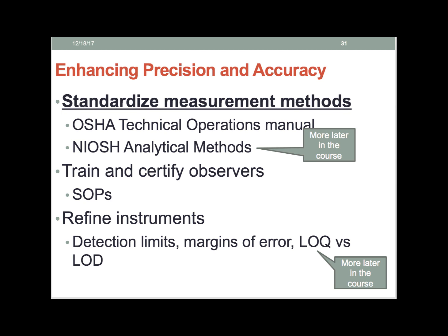And these can actually be easily confused with one another. So we may choose a different method based on the confounding variable of having too much dog hair in our environment. And for precision, precision would be ensuring that we pre- and post-calibrate our pump, that we handle our media in the right method that is appropriate for it before we sample, during sampling, and when we pack it up and ship it out. We can definitely influence our precision and our accuracy.